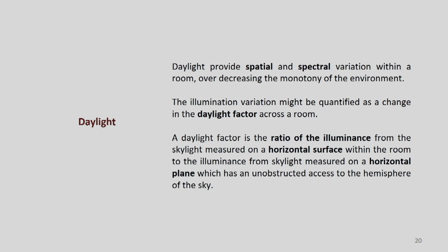Now, understanding of daylight and then utilization of daylight for designing is very important. Daylight provides spatial and spectral variation within a particular room, decreasing the monotony of the environment, because over the period of time it keeps on changing. The illumination variation might be quantified as a change in daylight factor across a particular room. So, what is a daylight factor?